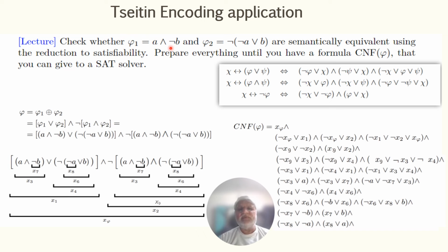That is how the Tseitin transformations will be taken through for different expressions. We make them into CNF, and then evaluate based on the input vectors. Don't get taken away when we mention input vectors. Does it become a dynamic simulation? No, it will not. Basically, we use the propagated values for evaluation, and this is in no way related to dynamic simulation.